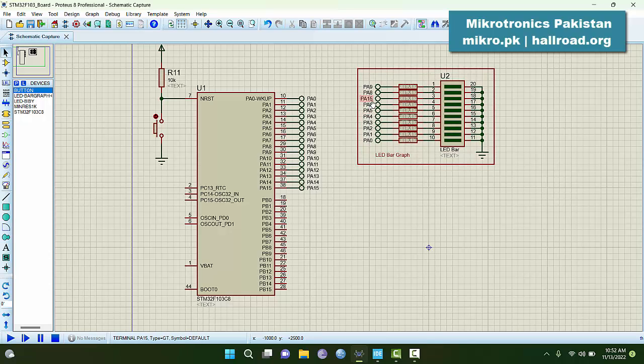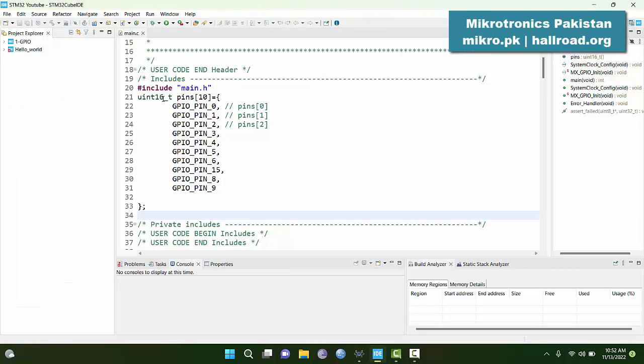Some are distributed to PA15, some to PA3, some to PA17, and not PA17, PA15 and 13, etc., or even to another port for that matter. It becomes really odd sometimes to remember their position and access them in a sequential or regular order. So this technique is good enough to put the pins in an order so that you can access them through their index number in the array.